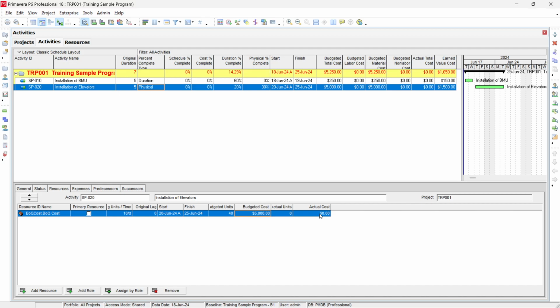Actual cost is what we actually have to pay to our suppliers or subcontractors. So as per earned value management, actual cost should always be computed by the planner or by the QS, who can take the actual data from the timesheets. If you allow P6 to compute the actual cost by itself, it will always override and we are not getting the results we are looking for.